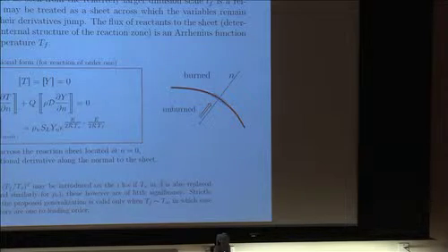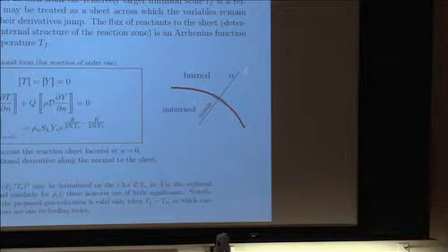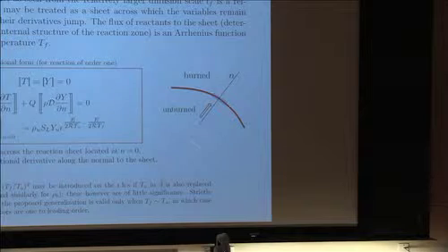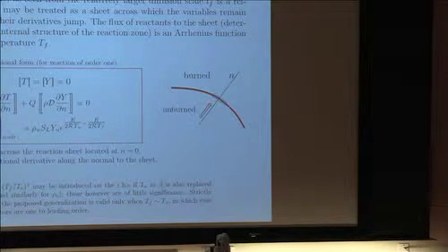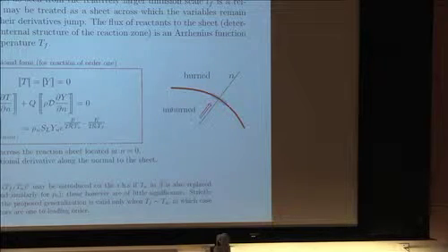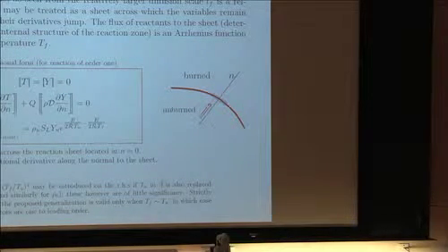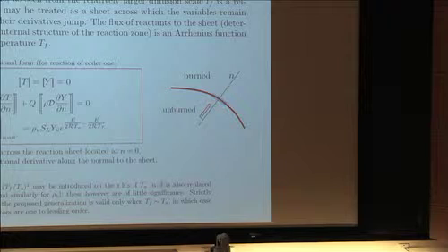And so the behavior of the flame in the direction normal to that sheet is almost like a planar flame, okay? And therefore, I can apply the same condition across this curved flame with two generalizations.